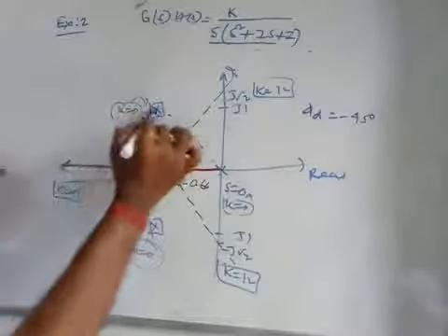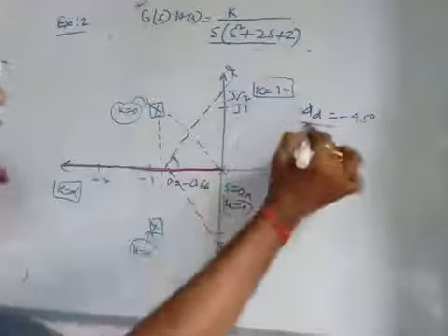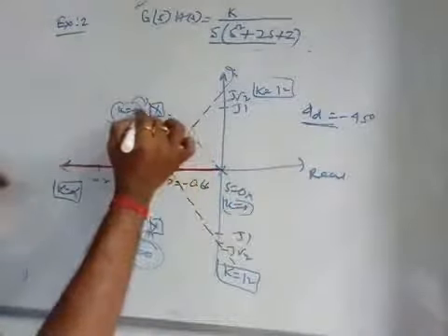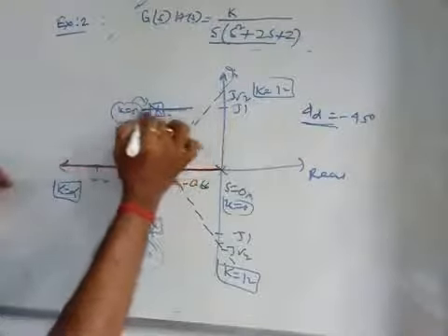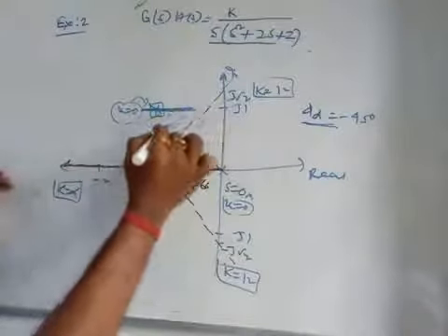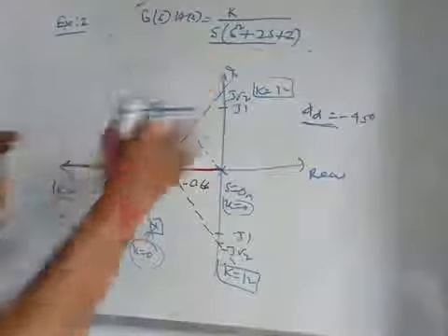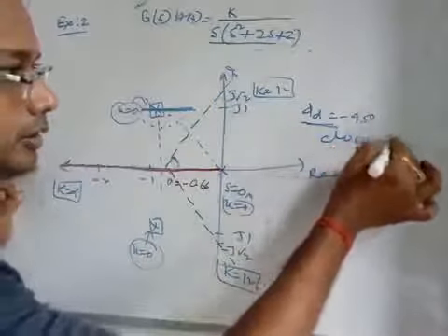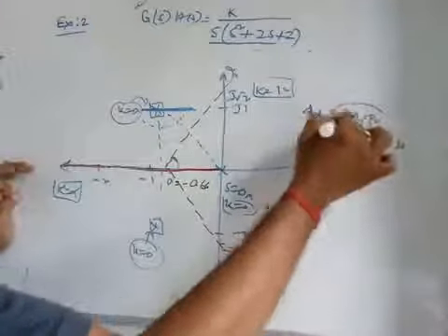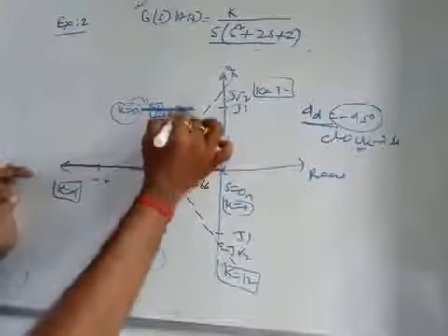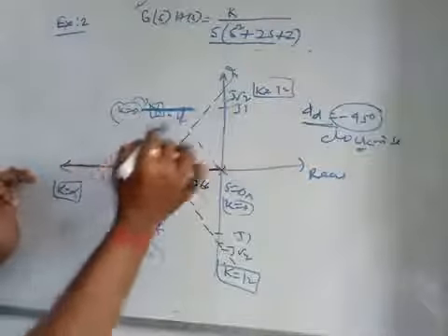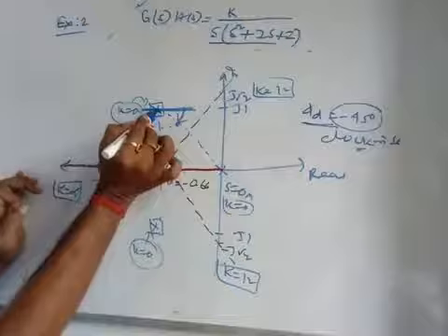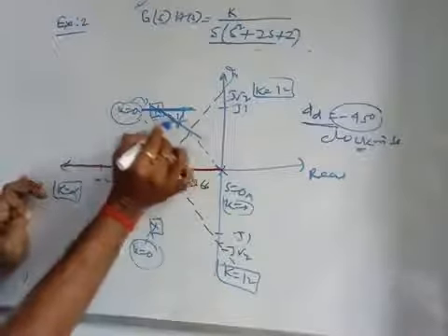So next step, you have to draw this angle of departure, minus 45 degree. Just make a horizontal line through this pole, put a protractor here and draw the angle clockwise. If you draw the angle clockwise, this gives a negative value, and through this point you draw a single line.